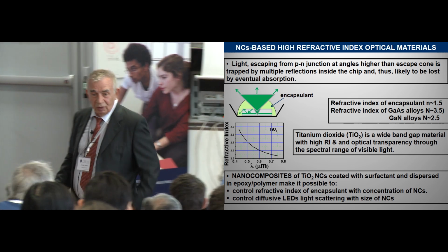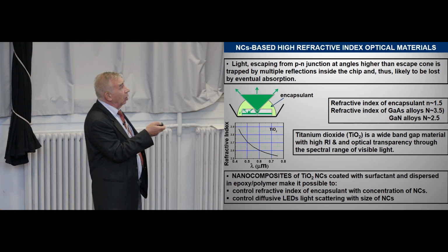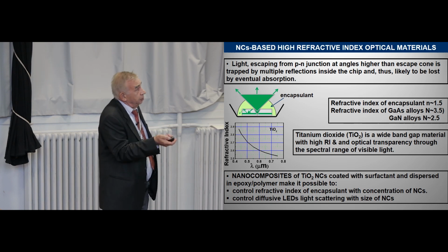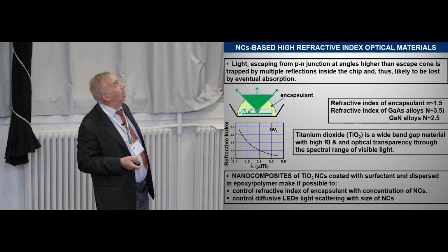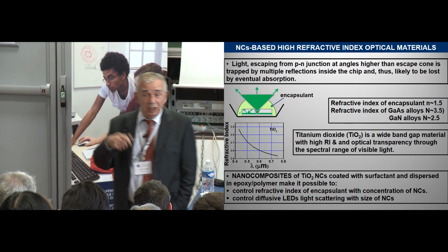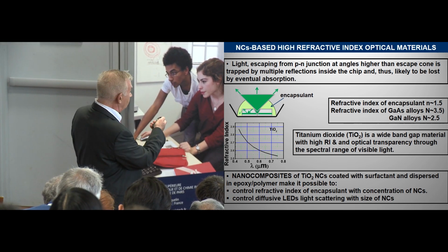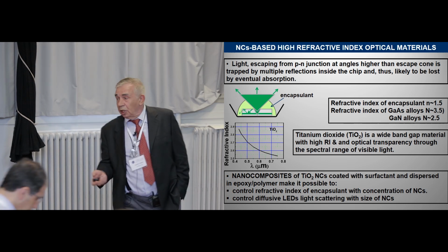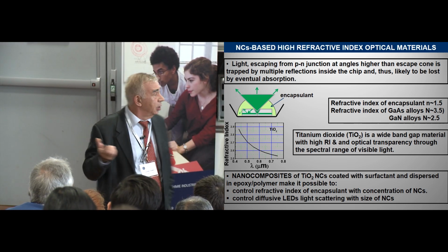You will touch your computer, you will see that it's always overheated. So what can be done? There are what's called high refractive index optical materials. If you increase the refractive index of the encapsulant, it should increase the light extraction from the LED.